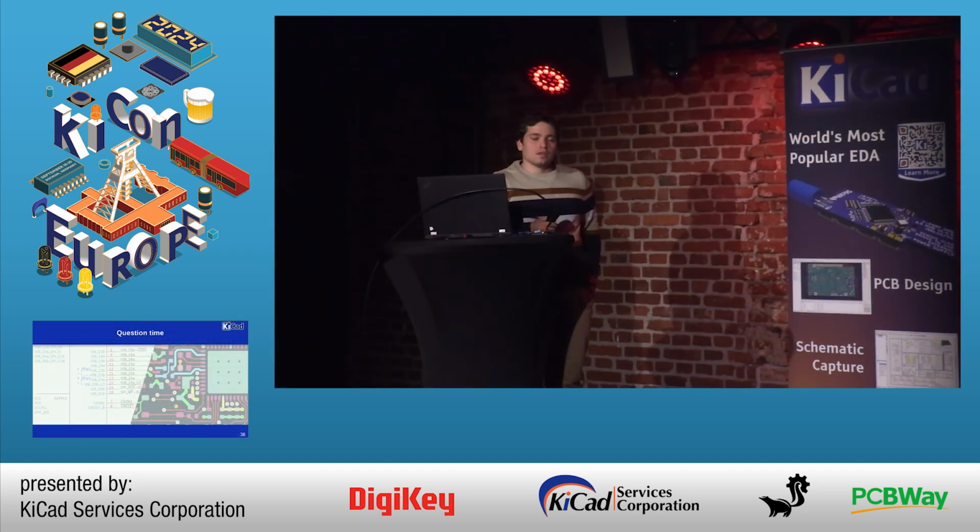Thanks for the talk. I have two questions. First, is KiCad able to check the distances between the layers? At the moment, in clearance or in creepage? In creepage, there's no check at the moment. And in clearance, you showed the stack-up, does it check the clearances within the stack-up? No, because it would have to know your dielectric properties anyway, because it depends on your dielectric. And I don't think there's anything coded for that anyway. Okay.